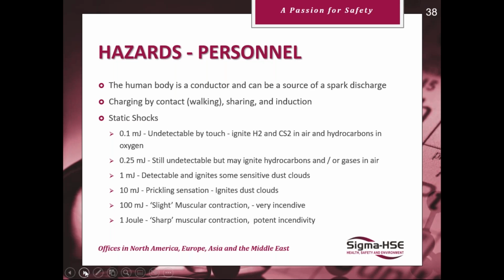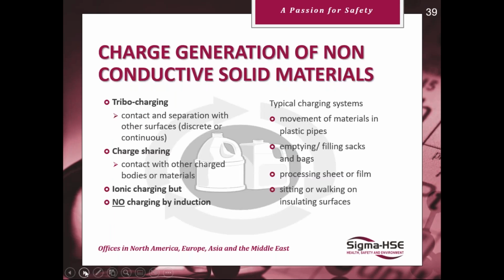10 millijoules is a prickling sensation, and you can ignite a lot of dust clouds. 100 millijoules is a slight muscular contraction, very incendive. And 1 joule is very sharp muscular contractions, very incendive. So, charge generation of non-conductive solid materials.